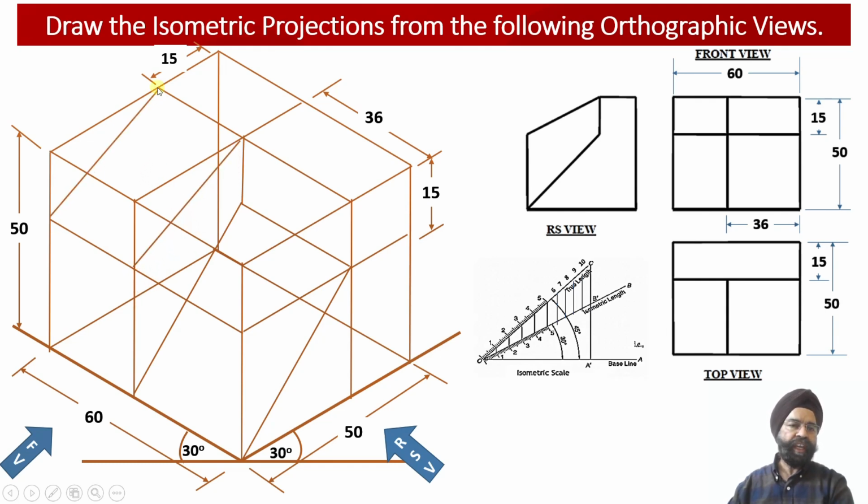So now if we join these two inclined lines over here, we will see the inclined web which is available with us towards the left hand side surface of the solid over here. Corresponding to this inclined surface, the side view will be projected as an inclined surface over here, and into the front view we are able to obtain the apparent shape of this inclined surface.